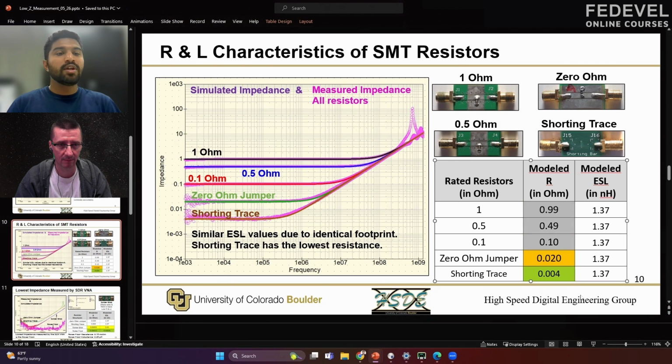And now it is good enough to establish confidence in the method that, okay, this is what we expected as a result of the DC 4-point Kelvin measurement. And we got all those 3 measurements within the same tolerance that we expected using the 2-port method. And this gives us enough confidence in the method.